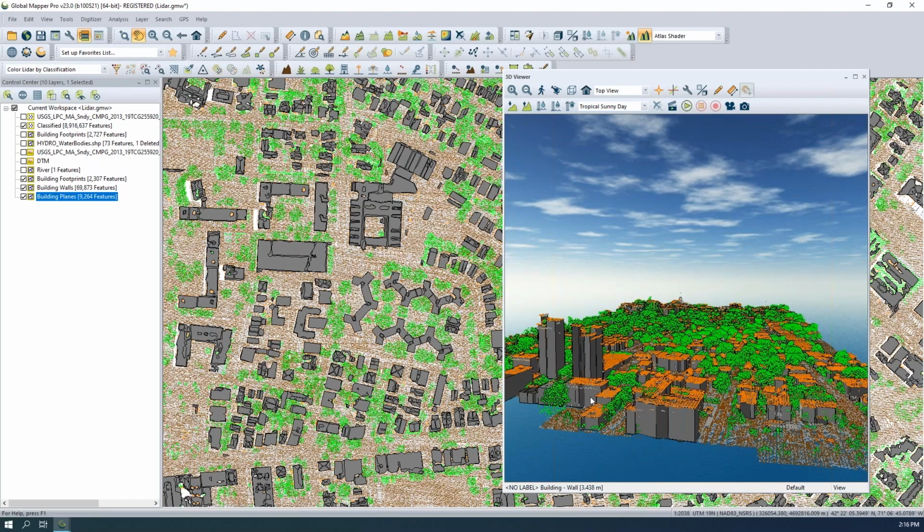Absolutely. Those can be used to flatten the footprints of the building areas. And when you're creating an elevation grid from point cloud data, especially classified data like this, you can filter to maybe only use the ground classified points. So you're really getting a more accurate terrain model and ignoring any vegetation and other structures on top.